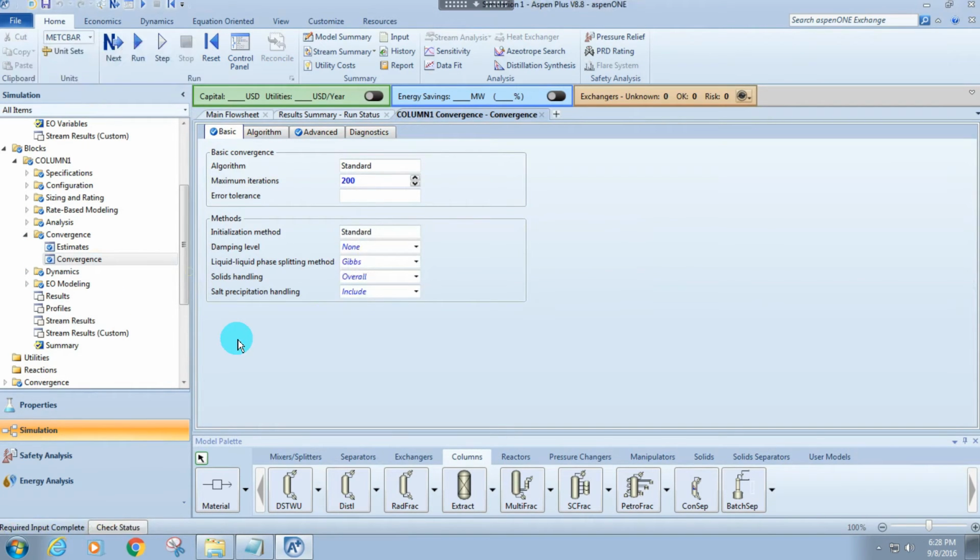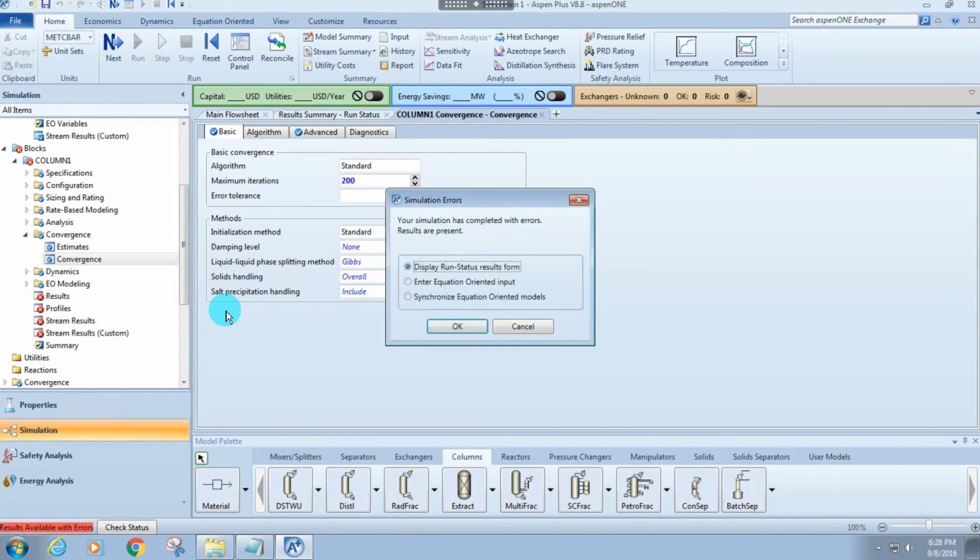Sorry, and we're still getting an error. So it's not an iteration issue, it's your specifications. Because if I input a distillate to feed ratio of 0.55, where all of that tetrahydrofuran is going to that distillate stream, it's physically impossible to achieve 100% purity of that distillation stream.